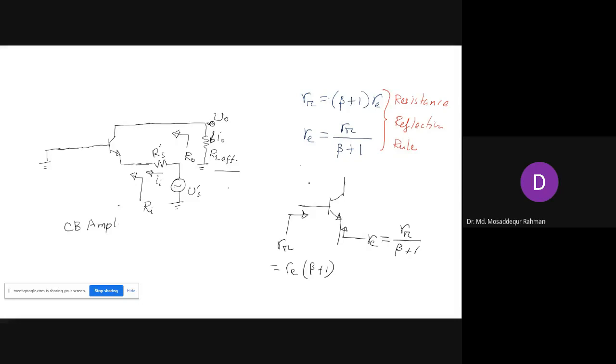The equations that are used to determine this are all AC parameters. See that in the hybrid pi and T models, these are transistor models for AC quantities. These are not in the DC model parameters. These are for AC quantities, so we call these AC parameters.